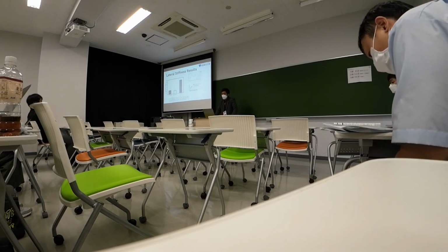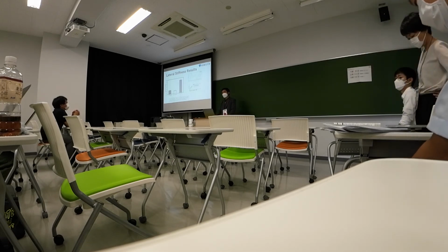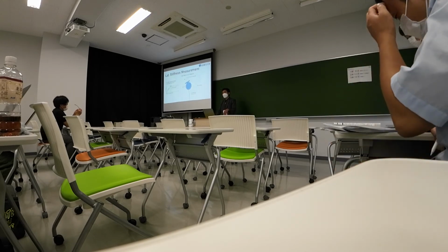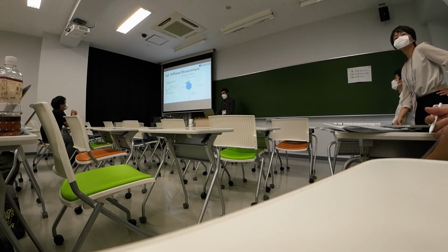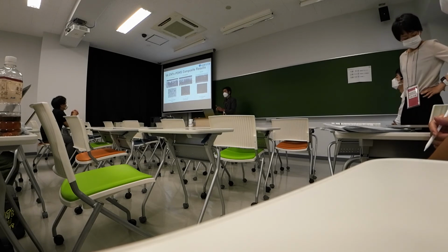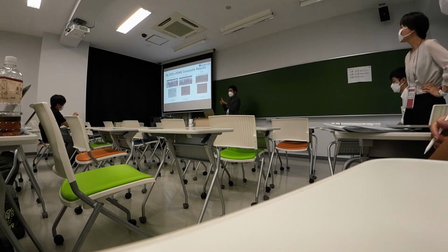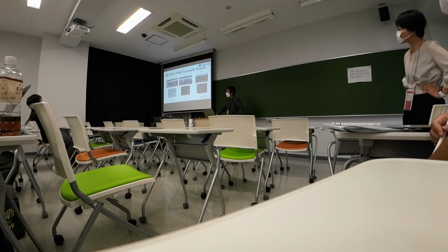Okay, sir. First, this one is stiffness. If we convert it, it will be Newton per meter. But this VACNT is so high because the lateral stiffness is based on lattice spacing. So the VACNT is here. The gap is really small, in nanometers, so it makes it steep, really steep, which makes a higher stiffness number.